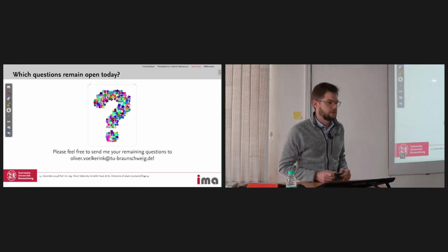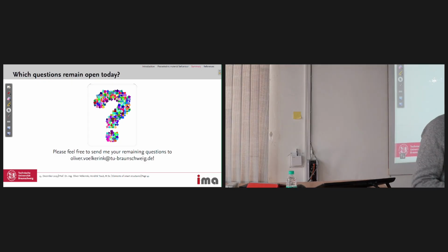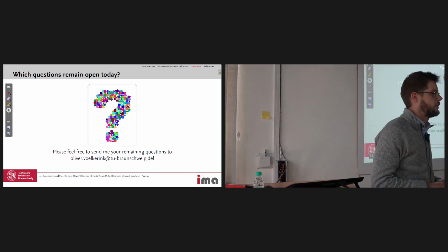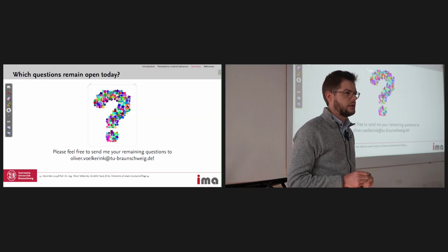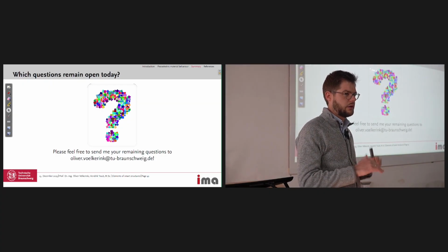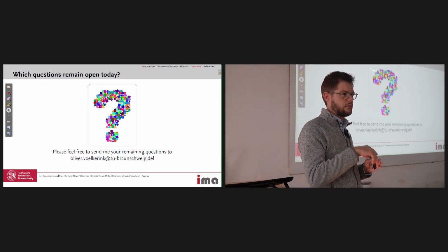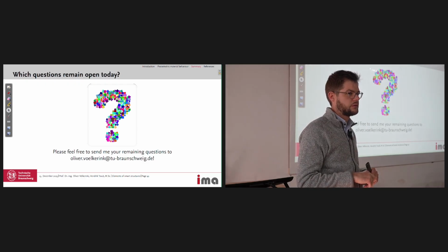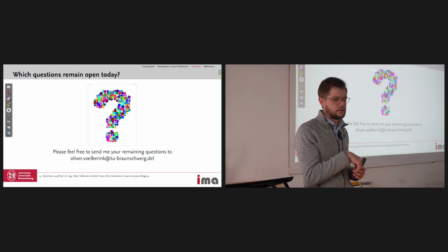Dynamic behavior, like alternating current. Does that create a lot of heat or operational problems? I think the piezoelectric material is quite good for dynamic behavior because you also use it for structural health monitoring, where you excite the structure with a burst signal, a sine wave with different amplitudes, and also collect it with the sensor again.